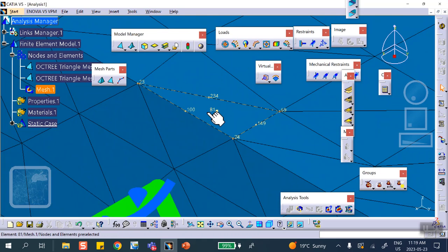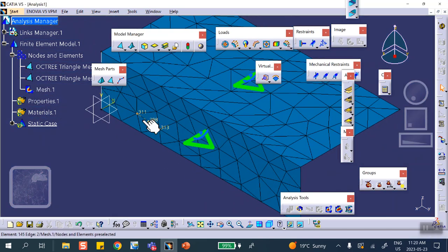If you zoom in, you put the cursor here. This element, for example, notice on the top along the seam, it's nodes 23, 124. When you look at the vertical one, the nodes are different node numbers. This is why if you do it like that and you actually pressurize the top face, these guys don't see each other, they have nothing to do with each other, and it will not run, as this will want to fly away. There's no restraint to hold it in that place. It will not run. I can guarantee you that.